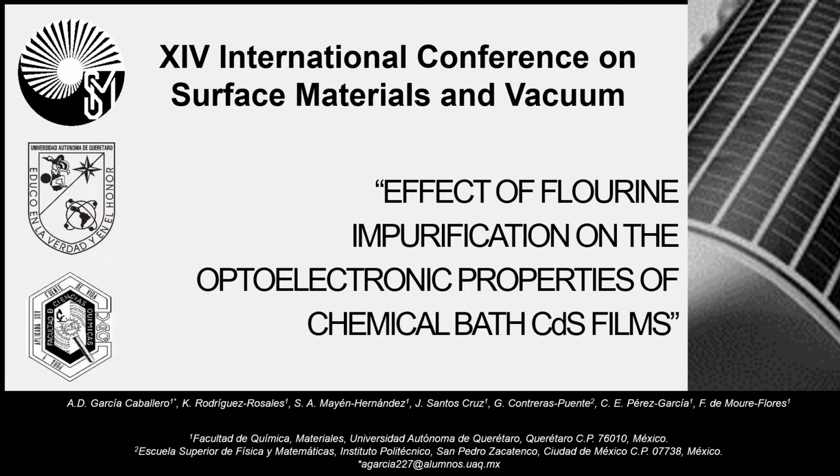At two different temperatures, growth on commercial glass FTO substrates, and the CdTe or cadmium telluride films were deposited by closed space sublimation or CSS to form a thin film heterostructure. We evaluate the influence of fluoride in different concentrations with a solar simulation by current versus voltage measurements. Electrical and optical properties were also evaluated.